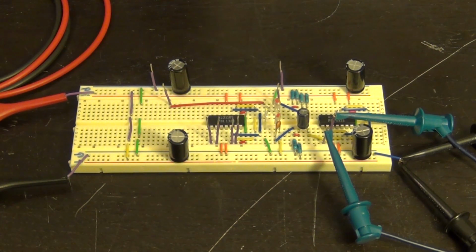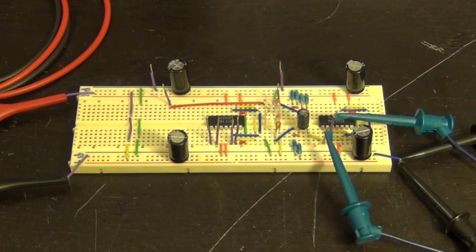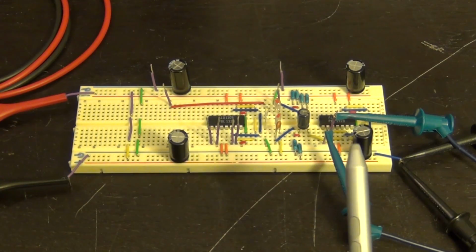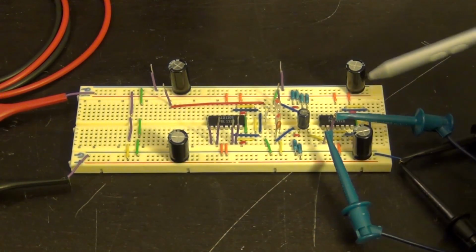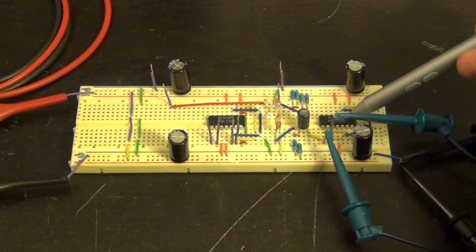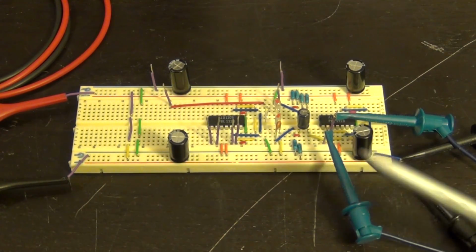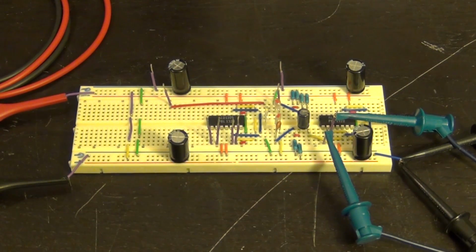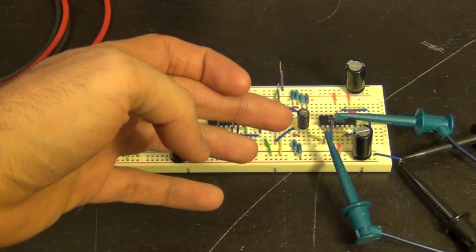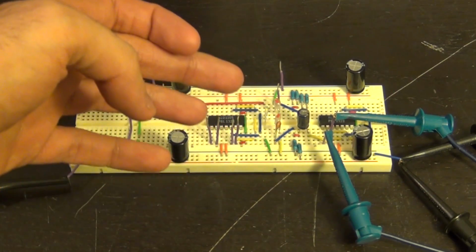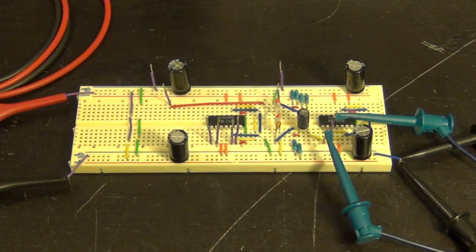So here's our setup for measuring the CMOS inverter. There's a lot of stuff on here. What did you build? Okay, so let's ignore most of this for now. The only thing we should look at right now is this chip. That's the ALD1105 chip that we showed. And this is basically the input and output of our inverter. So by putting a voltage sweep at the input of the inverter and measuring the output voltage and characterizing all of that on the instrument, we should be able to do some of our calculations.